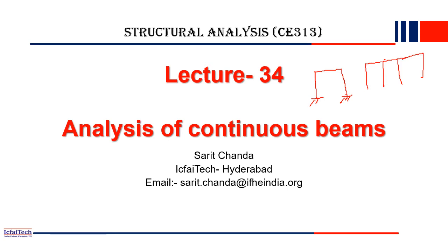If you look at our FST campus, you will find so many columns, and the beams are continuous. This beam is a single continuous beam. Whereas whatever we discussed up to the previous lectures, we considered only a single bay beam, and that too a determinate structure. That means only using the three equations of equilibrium we can solve the structure. Solve in the sense we can compute the bending moment diagram, shear force diagram, slopes and deflections.